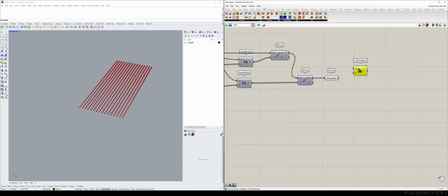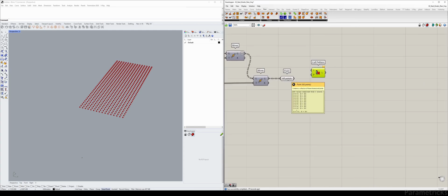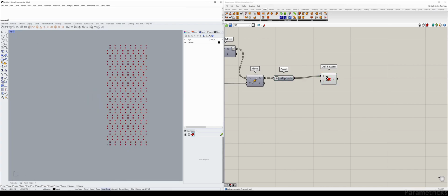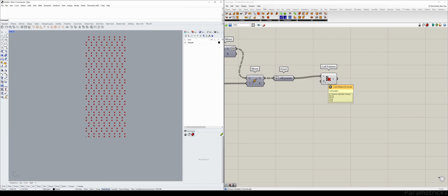Yeah, we use the culling pattern. From this point, what we want to do is actually reflatten our points because we don't need that hierarchy anymore. So the list to flatten, the list to reduce is that. So without doing anything, let me switch to the top view. Because the cull pattern comes with a false, false, true, true pattern already, you can see that we only have half of this, 304 points.